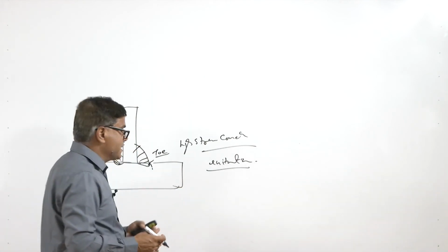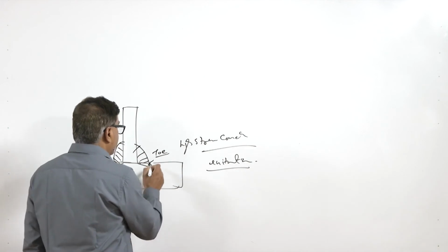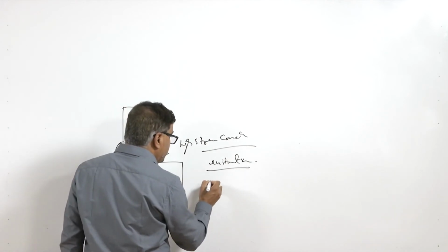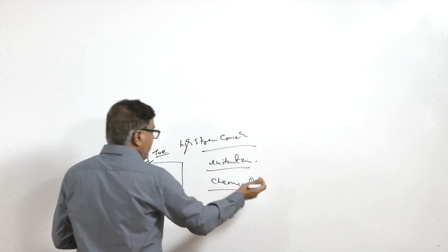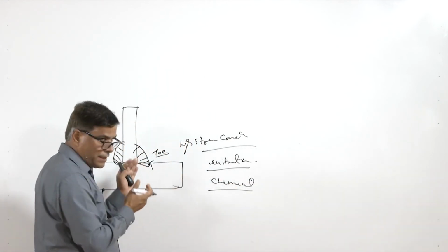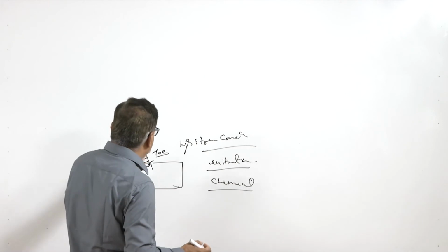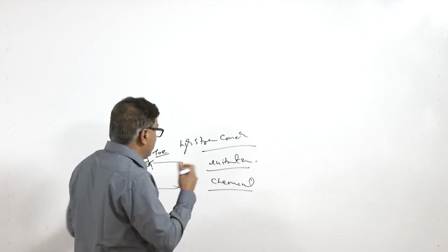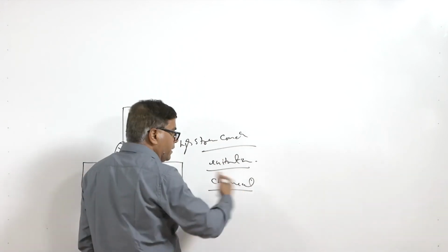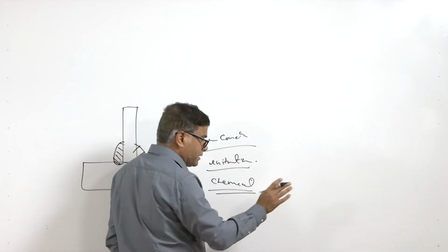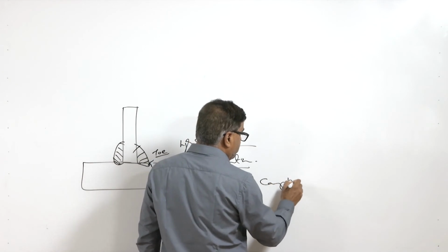But why it has taken place, for establishing that we need to study all the aspects. From the macroscopy we can easily see that this is the region of high stress concentration, but to establish why it has not tolerated the crack nucleation, we have to carry out an extensive study on various aspects, which may include chemical composition.